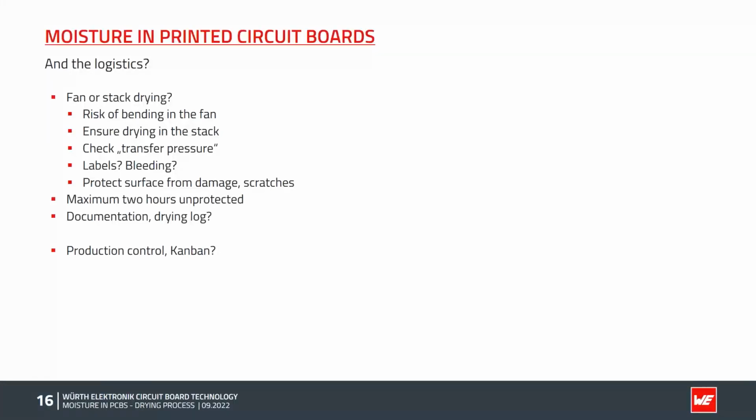Should you use a fan for the drying for the PCBs, or use a stack for the drying? If you use a fan, there's always a risk of bending in the fan, which is not that good for the population of the components, of course, and the soldering process. If you use a stack, you must ensure drying in the stack, so the PCB in the middle of the stack should dry sufficiently.